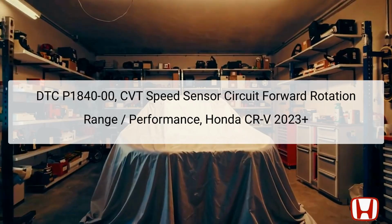Welcome to our troubleshooting guide for the DTC P1840-00, known as the CVT Speed Sensor Circuit Forward Rotation Range Performance Issue, specifically for the Honda CR-V model year 2023 and later. This diagnostic trouble code indicates a mismatch between the driving conditions and the detected voltage level from a continuously variable transmission, CVT speed sensor. When discrepancies arise, the Transmission Control Module, TCM, identifies this anomaly and generates the DTC.